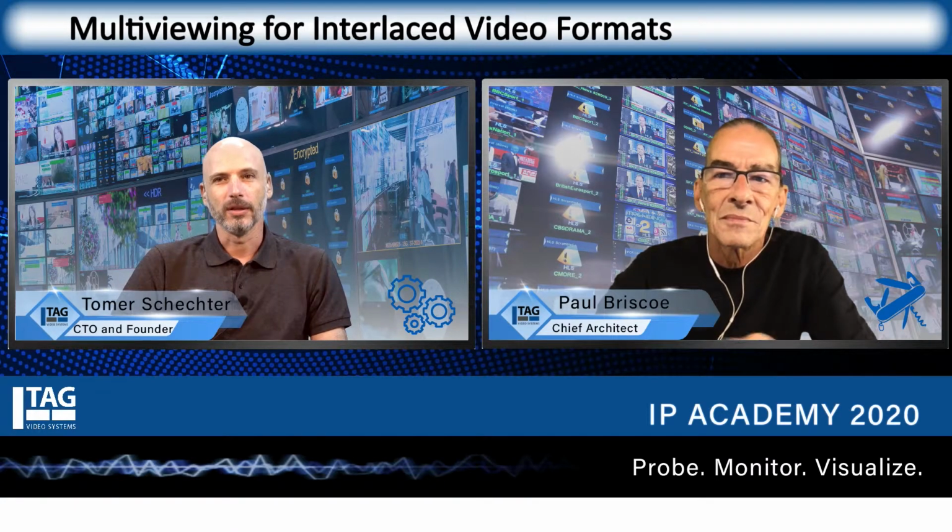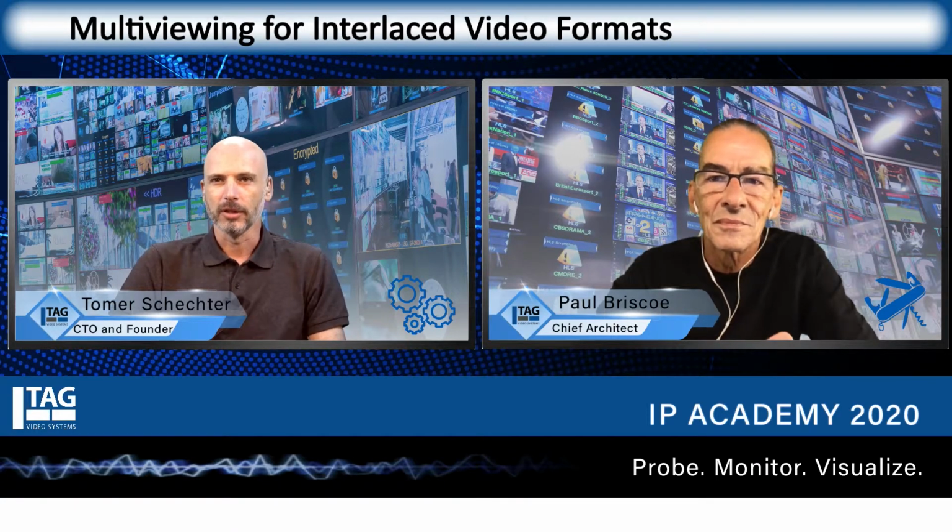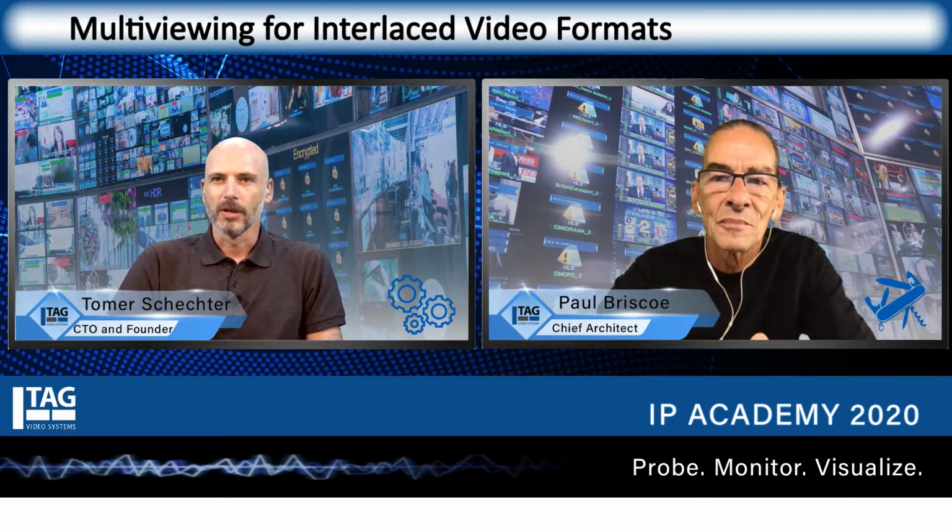But when you're talking about upscaling, then the upscaling itself, again, is interpolation of the information that you have. The deinterlacing is another interpolation. And the combination of the two together is a huge interpolation. And what you really have in the original content is just a very, very tiny piece of what in the end you have in the whole picture. So in those cases, it can be quite a degradation of the quality in the end.